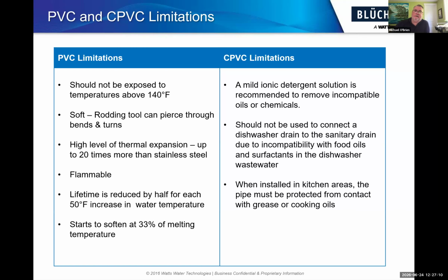So when installed in kitchen areas, the pipe must be protected from contact with grease or cooking oil. So yes, it can handle the temperatures, but again, if you have a cleaning process and you have proteins and food oils, you're starting to destroy your drainage material.